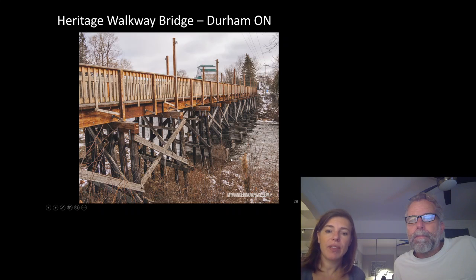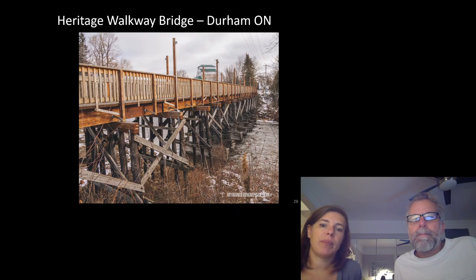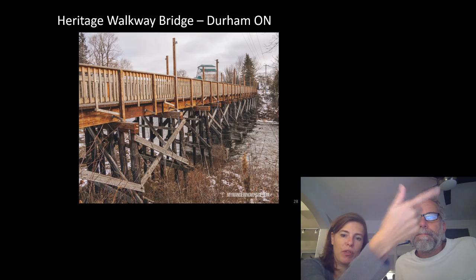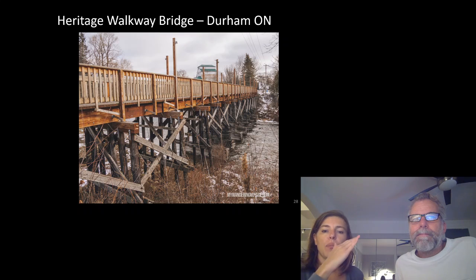And this looks so busy because wood, as we've seen, is kind of our weakest material. But it's cheap and easy to build with, so you can bring it into sight. What they have is a series of freestanding piers lined up side by side. These bracing members that make it look so busy are keeping those from all just tipping over like a set of dominoes in every kind of kids movie or classic movie you've ever seen, where you've got a series of elements and one tips over and they all go down. So these are bracing those together to prevent that from happening.